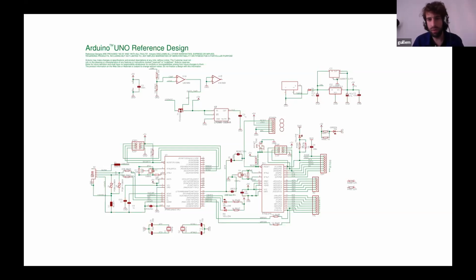Well, to do so, actually, we could do two things. As I said, you could build a programmer, you could build a specific kind of hardware that talks, for example, USB, and is capable of flashing that microcontroller. But that means that you'll need to always carry this small piece of hardware with you when you want to flash a microcontroller. So what we usually tend to do is to put a piece of software inside our microcontroller, inside the ESP32, that allows the ESP32 to be programmed in a much more convenient way.